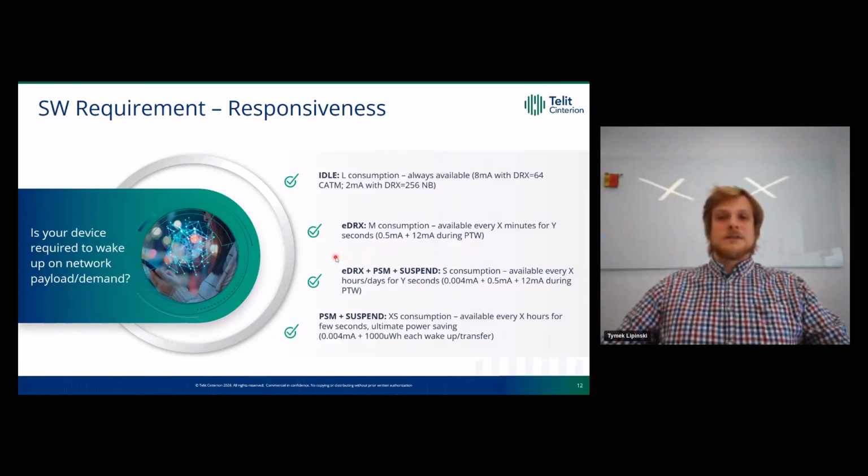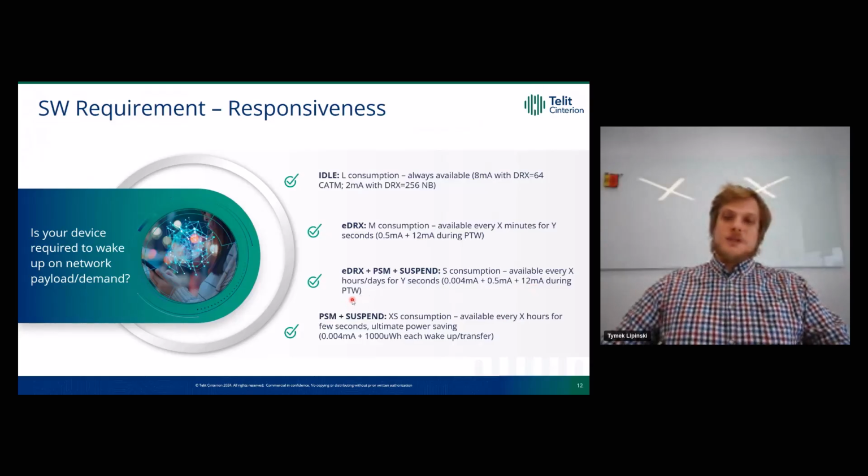Then we have an extra evolution of the system, very small consumption, so it's eDRX joined with PSM and Suspend. So the modem will be available every X hours or days for Y seconds. During those X hours or days, the consumption goes down to 4 microamps or even lower. And when we are waiting for signal, it's 0.5 milliamps. And when we are actively listening for the signal, it's 12 milliamps for a very short period during the paging time window. PSM and Suspend. So this is the best solution.